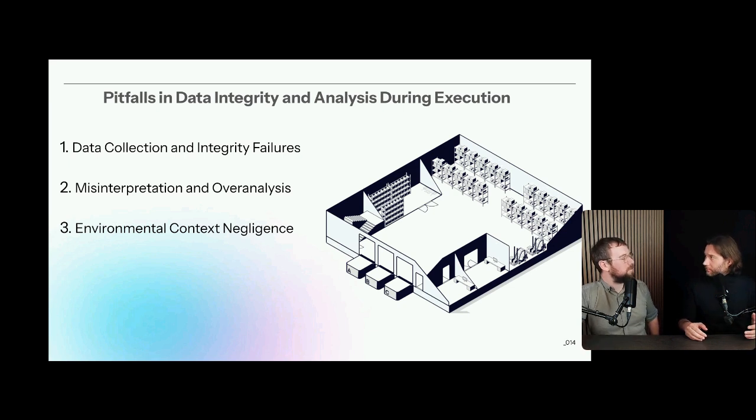Operational shifts, right? Maybe we have more people working in a huge warehouse in the morning than in the evening. How does this affect the temperature of the goods that are stored? In those bigger warehouses there is the loading or unloading of goods, and you have a certain frequency throughout the day. So you need to be aware of the frequency of those operational activities throughout the days or weeks, and plan your mapping accordingly.